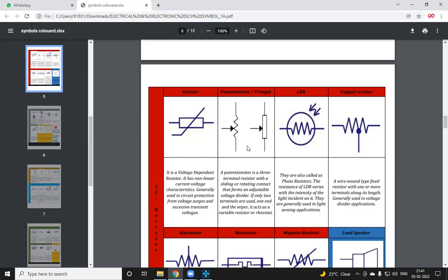There is a short description on DigiKey. Every component there has a short description. That is the best name. You can cut and paste from it, add many more things, and edit that name as needed. This is called experience. The concept I told you is that the component name should have enough information to identify what it is, what the value is, and what the package is.